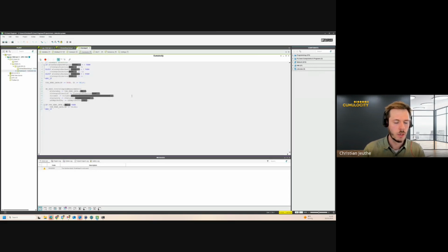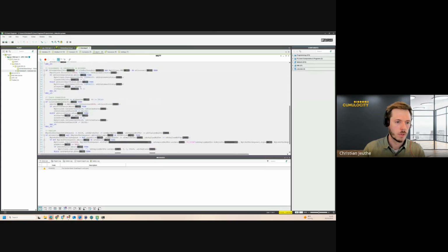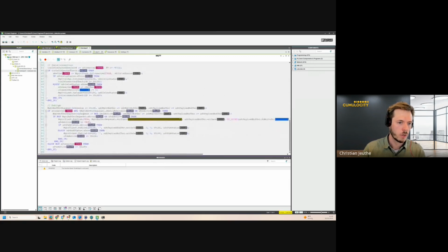There's a Cumulocity tab that's creating some variables and an MQTT session that's going to be invoked. So we have a publish command for the MQTT client that publishes the data to the ThinEdge endpoints. And we are seeing that live as we're in the debug mode. Occasionally the topics from the ThinEdge MQTT broker pop up, like TEDge/measurements, etc. That's basically the entire chain of sending the data to the ThinEdge MQTT topic from the PLCnext Engineer project, and then everything from ThinEdge is there and just ready to be used.